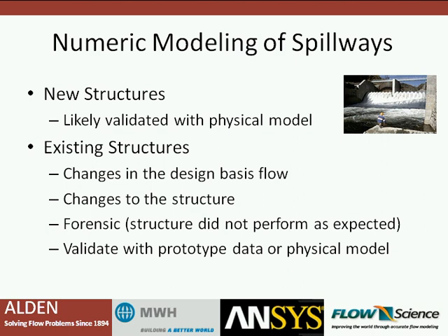On a new structure, we would use CFD typically to pre-screen a number of alternatives and see which ones are going to be best suited, and then that alternative would likely be tested in a physical model depending on the risk associated with that particular design. On existing structures, going back to what Mario said earlier, there's a lot of existing structures where there's changes in the design flow for the various reasons that he highlighted, and those can result in the potential need to make changes to those structures as well.